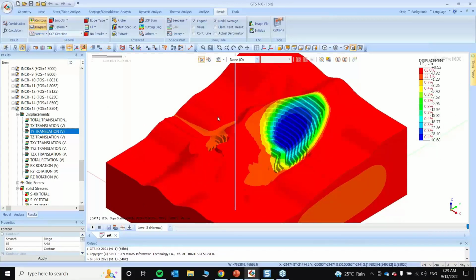Since this is a 3D model, the results you are getting will be in 3D format. But do remember, in actual site conditions, the bench or the particular high wall might fail if any one of the three criteria has been met. That is why we put very stringent threshold values for high wall monitoring. Okay,